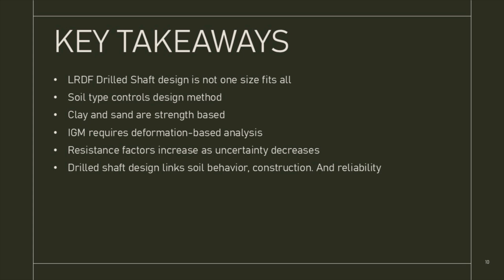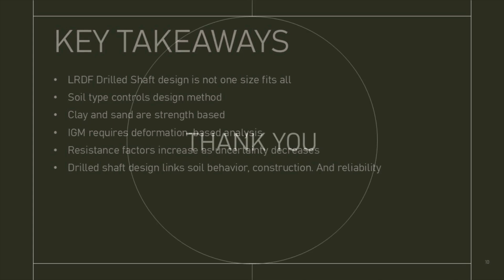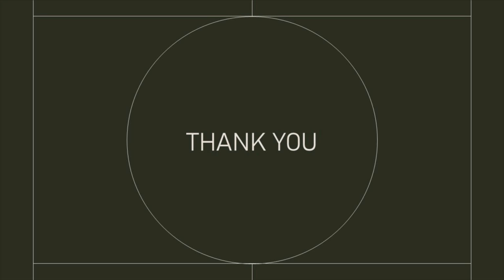Together, these case studies show how LRFD integrates soil behavior, construction effects, and engineering judgment to produce safe and rational drilled shaft designs. These 5 examples show that LRFD drilled shaft design is not one-size-fits-all, and that soil type, load transfer, and uncertainty drive both the design method and resistance factors.